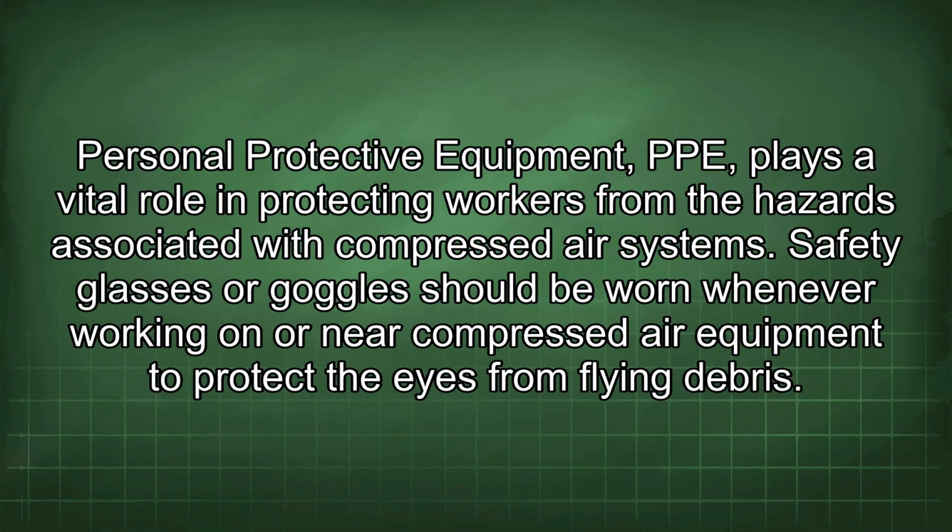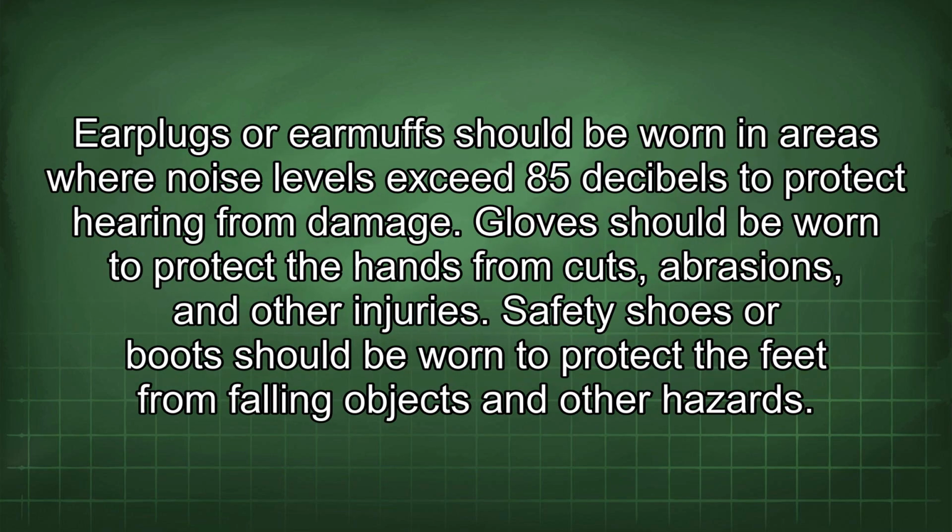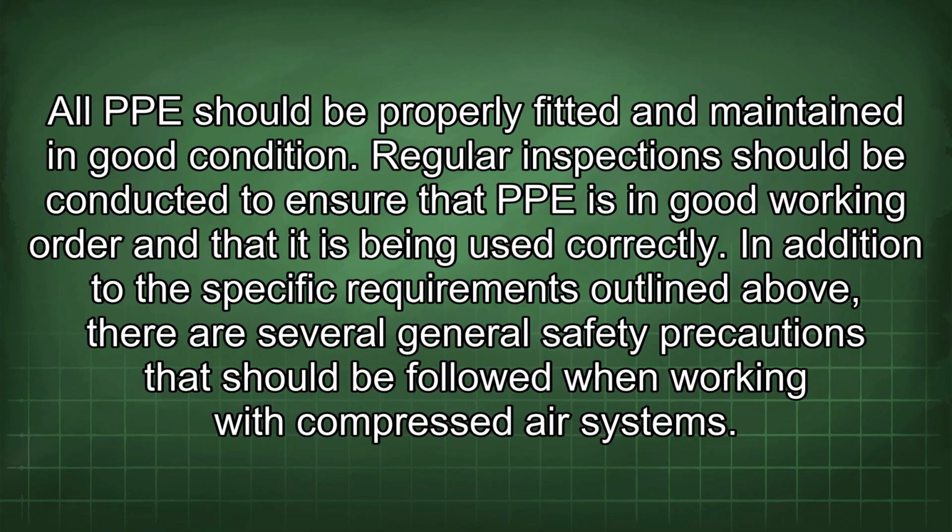Personal protective equipment (PPE) plays a vital role in protecting workers from the hazards associated with compressed air systems. Safety glasses or goggles should be worn whenever working on or near compressed air equipment to protect the eyes from flying debris. Earplugs or earmuffs should be worn in areas where noise levels exceed 85 decibels to protect hearing from damage. Gloves should be worn to protect the hands from cuts, abrasions, and other injuries. Safety shoes or boots should be worn to protect the feet from falling objects and other hazards. All PPE should be properly fitted and maintained in good condition.